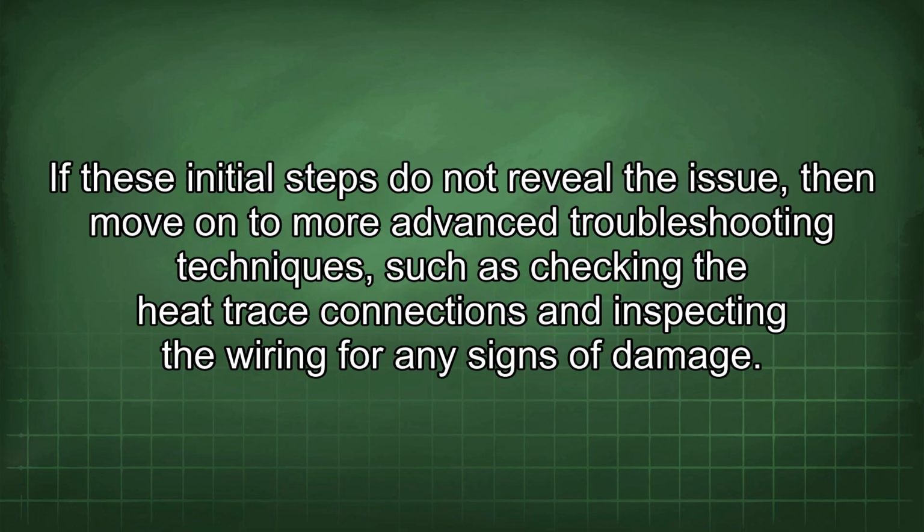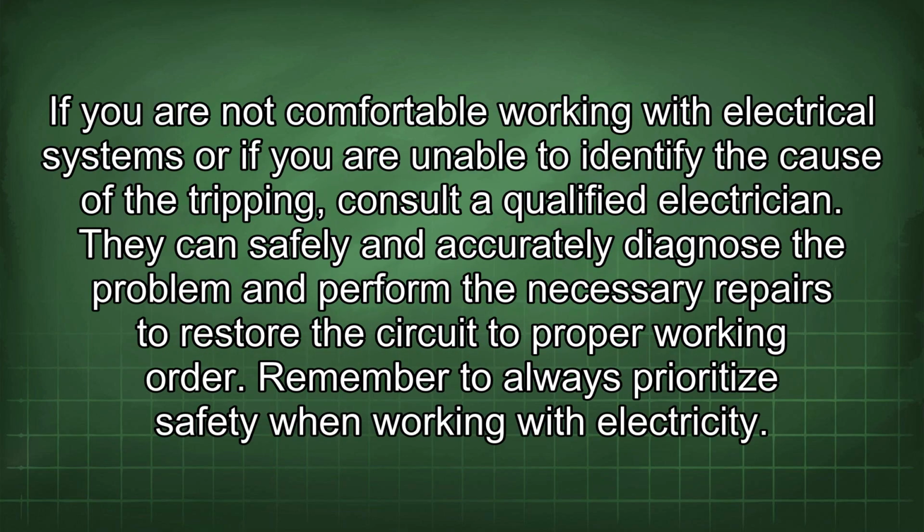If these initial steps do not reveal the issue, then move on to more advanced troubleshooting techniques, such as checking the heat trace connections and inspecting the wiring for any signs of damage. If you are not comfortable working with electrical systems, or if you are unable to identify the cause of the tripping, consult a qualified electrician. They can safely and accurately diagnose the problem and perform the necessary repairs to restore the circuit to proper working order.